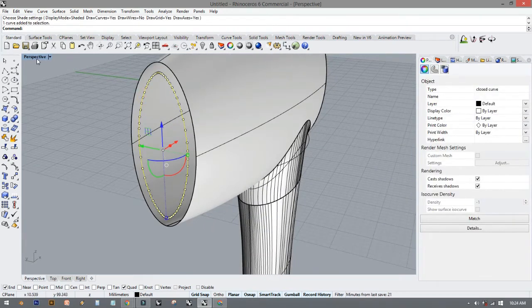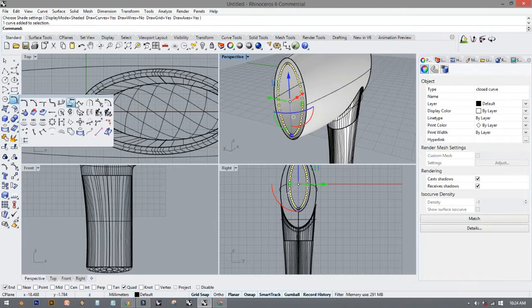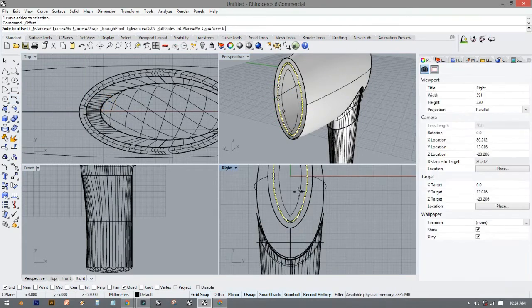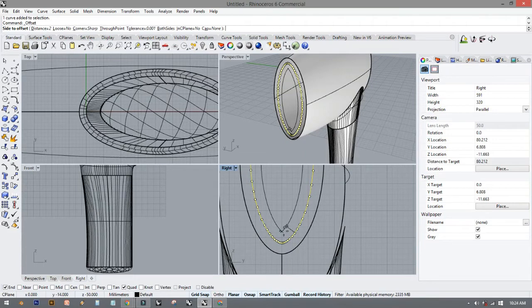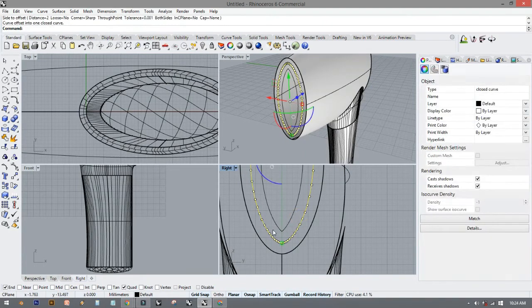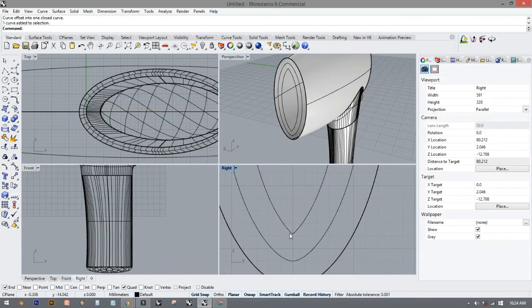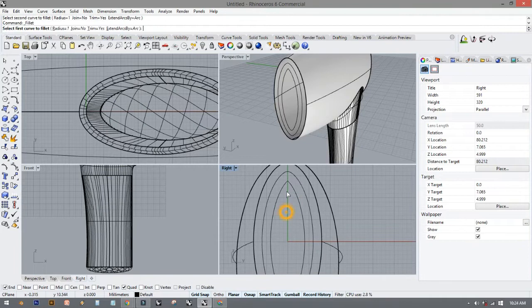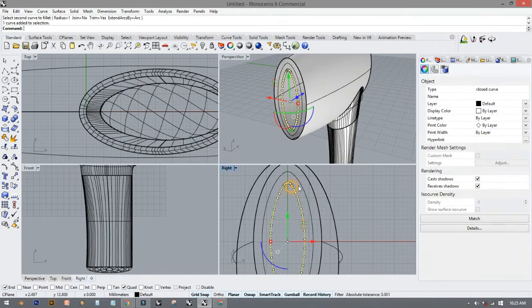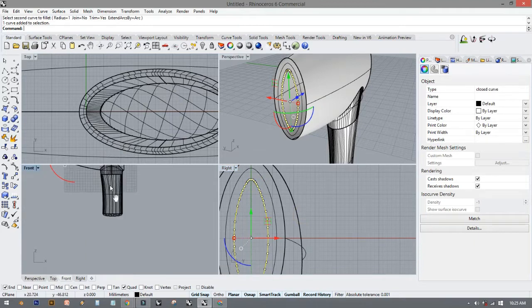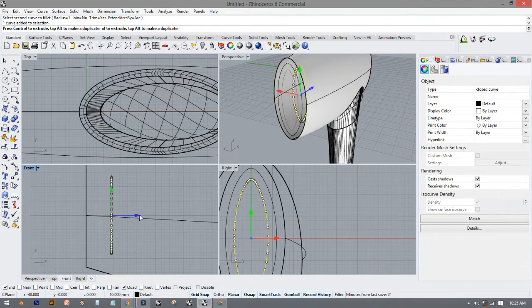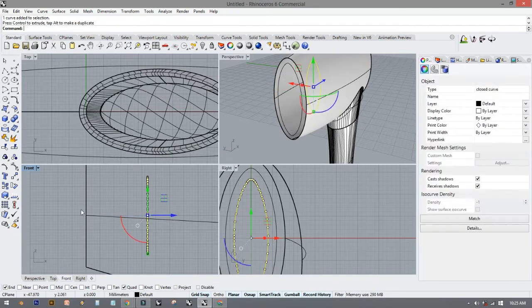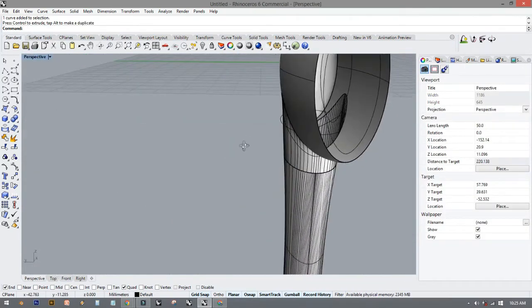Now this part here, remember this one. I'm going to frame on the offset group also, but this time it's inside. As you can see, there's a problem with this part here. So we are going to use the fill curve, change to number one. Then we just click on this part here. I will bring it inside like that, and you can see this inside.